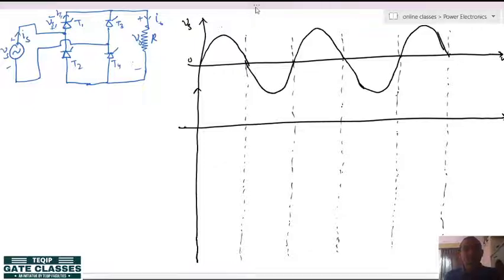So, now here this is my pi, 2 pi, the black markings are showing the multiples of pi instants, and let me show the thyristor triggering angles also here. So, let us say this is the triggering angle alpha, okay. Now you have to remember that in half wave, only in one half cycle, the positive half cycle, I have provided the firing angle.